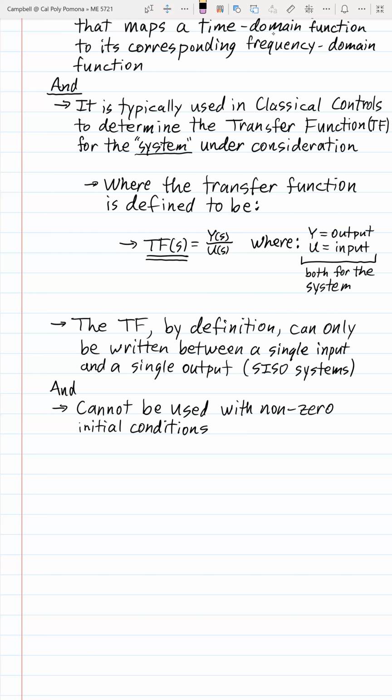So that was one way to get a dynamic system to do something, was to give it non-zero initial conditions. Another way, of course, was to excite it with some kind of forcing function, some kind of input. And that's what transfer functions assume, that the only excitation for the system is coming from a forcing function or an input, and that nothing is happening because of initial conditions. All the initial conditions are zero. So that's another limitation for these transfer functions, and clearly a pretty important one.